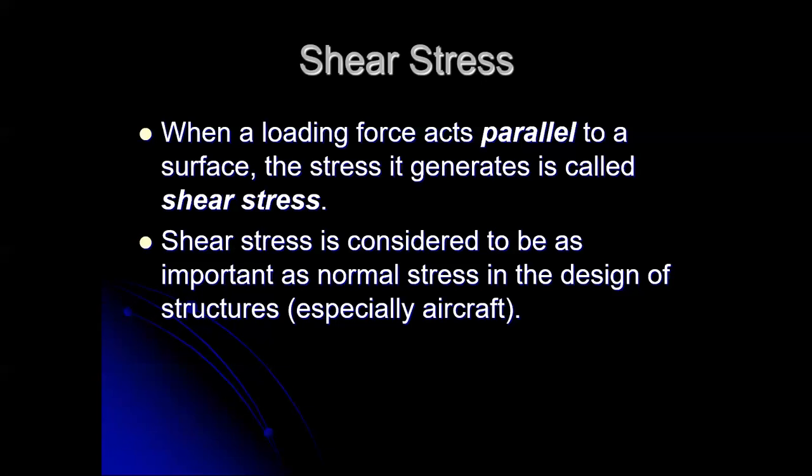In an aircraft, we use shear stresses as one of the main ways that we handle forces on the structure. Every single lap joint that we have between skin sections, between different parts of structures put together, anytime we've used a rivet, we are working with shear stresses.